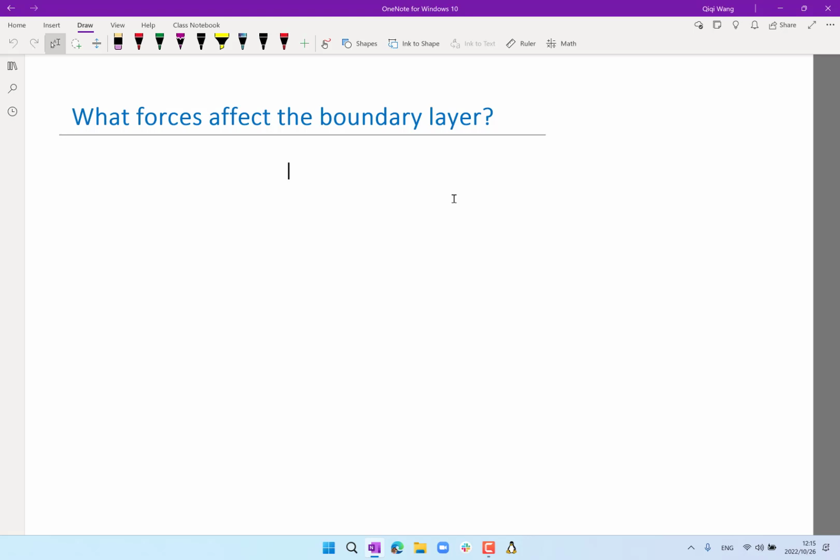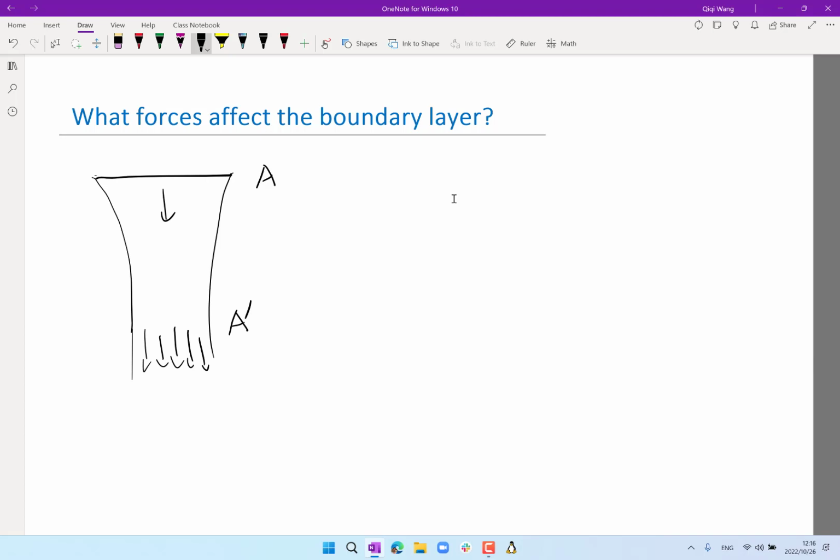let me just take the example we just worked on for a helicopter, right? So if you look at the helicopter, so that's the rotor disc, area A, and the flow shrinks in area into A prime, and the flow goes basically parallel over here. So you might be tempted to use Bernoulli and say, okay, because the velocity is equal to 0 and the velocity is equal to W over here, the flow goes faster, therefore it has a lower pressure. That's not the case, right? Why is it not the case?